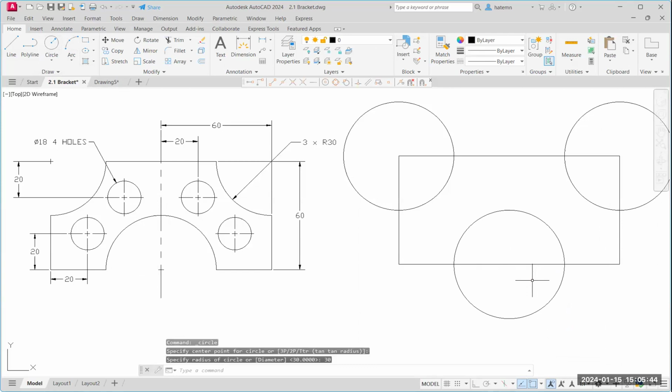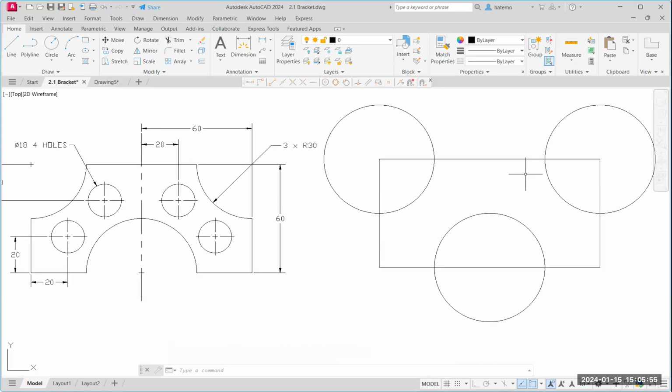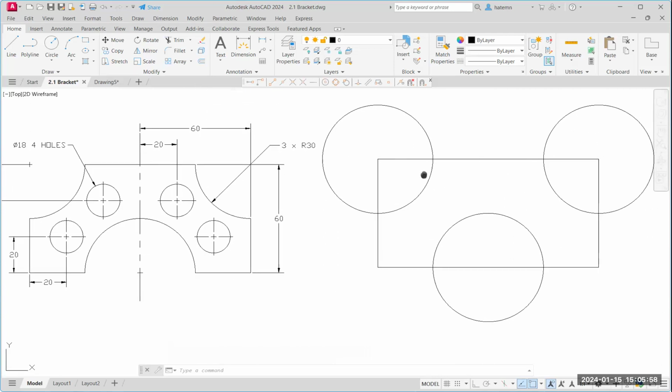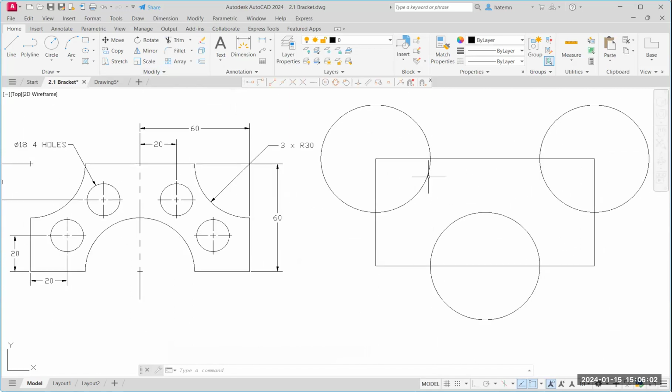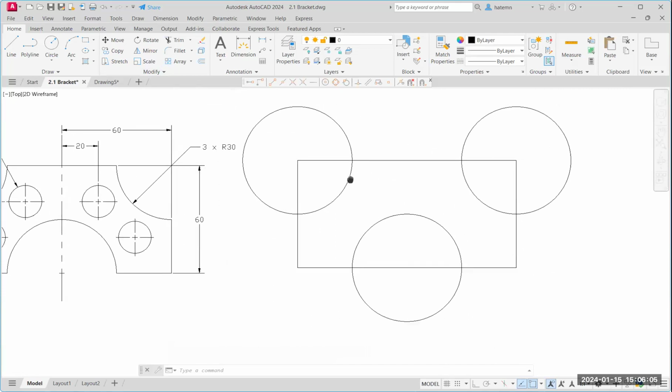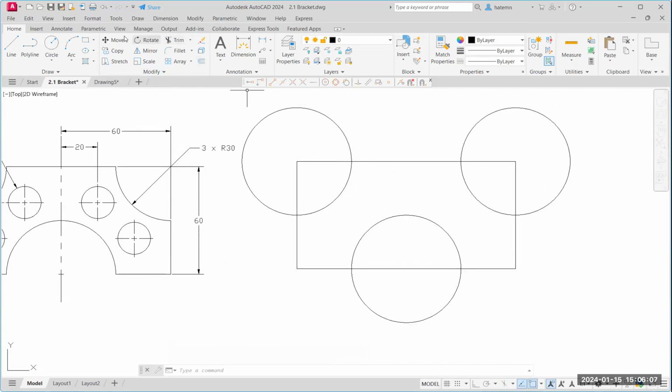So at this point, I know I want to keep only part of this circle. I want to keep this large arc here and this arc here. So I'm going to modify my drawing. I'm going to slide over here. If you have a 3-point mouse with the roller button in the middle, you can zoom in and out. I'm pressing down just to slide it over for us. I'm going up here and modifying something that's already here, so edit something in your paper or model space.